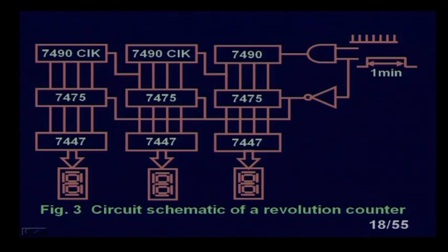So automatically, if 1 is coming, the J input gets 1 and the K input gets 0. If 0 is coming, J gets 0 and K gets 1, so it is inverted. Under the clock pulse, in a master slave, the trailing edge clock is activated, so the entire change occurs at the trailing edge, and whatever data input you have, either 1 or 0, it will stick to that.